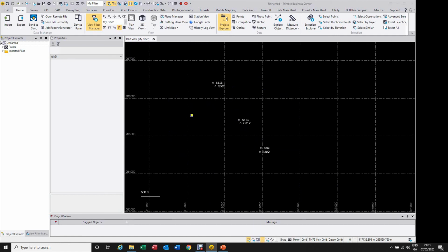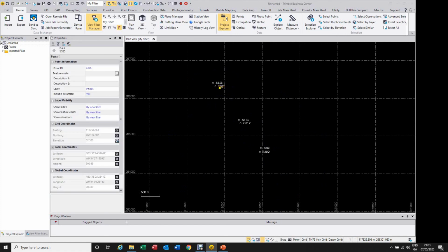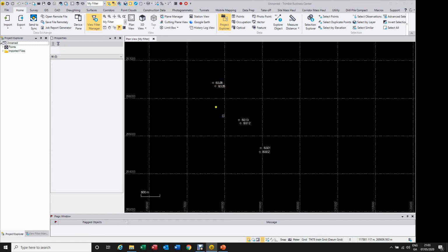But with the points, there was a way to export them with the global coordinates and then bring them in, and then transform, or using these common coordinates between the two systems to determine the grid coordinates. So that was one way using Trimble Business Center.